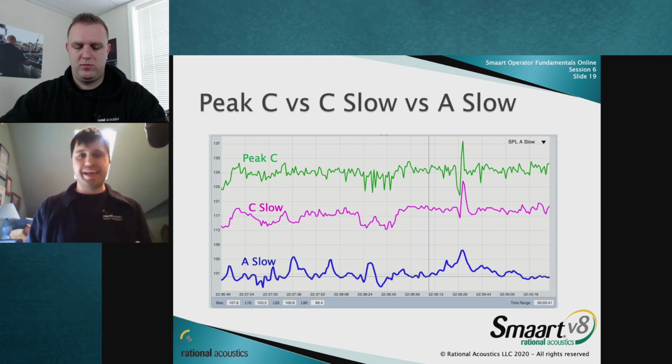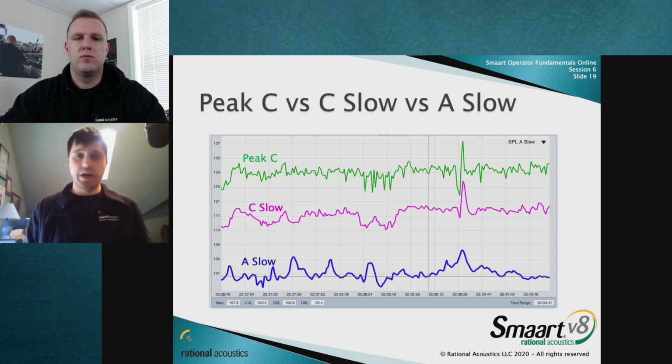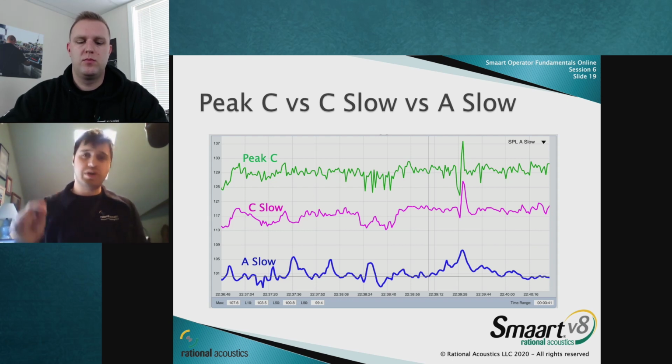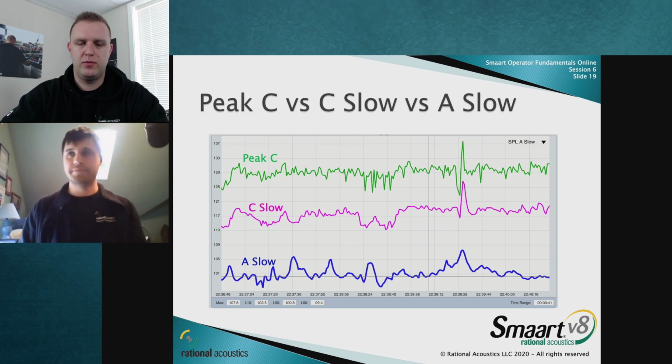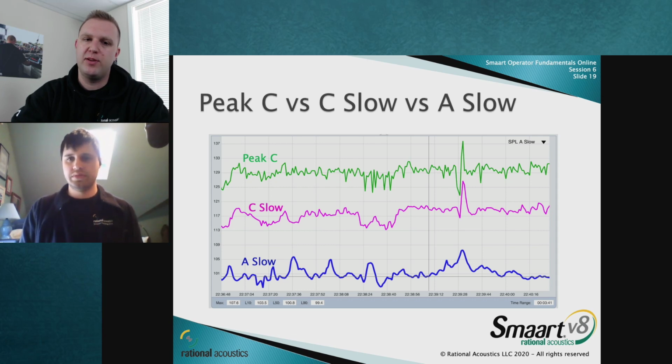And so if your mic can't handle those levels that are 135, 140, you're going to clip. And clipping is a really bad thing when we talk about logging SPL, because as soon as we log a clip, your data is invalidated, and all those LEQ buffers have to flush, and so now our data is no longer reliable. So it's very important that we don't clip when we're doing this, and that's why we recommend having a mic that can handle up to 140 dB SPL. Great. And just for those following along, this graphic here was created from Smaart's SPL history timeline, which is available in both Smaart version 8 and Smaart SPL.